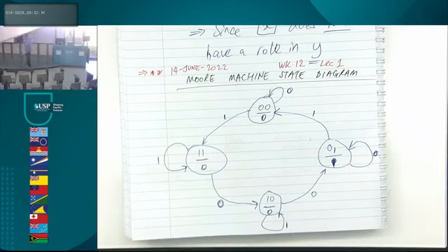And it's also giving you another piece of information. When we draw this state diagram, it's giving you the value of the output. So in order to accommodate some possible outputs, you may have to add an extra state. Let's say there's 0, 1, output 1, and another one with 0, 1, output 0. So you have to have two bubbles to accommodate that. Because remember, you are showing 3 pieces of information.